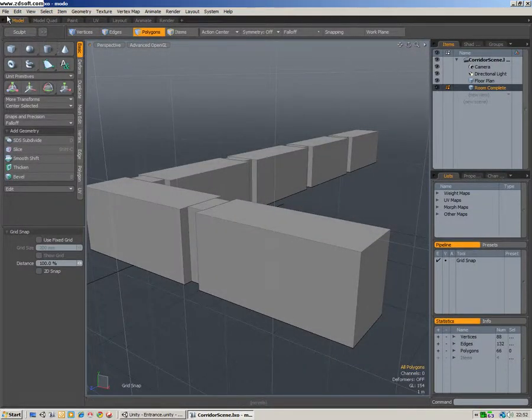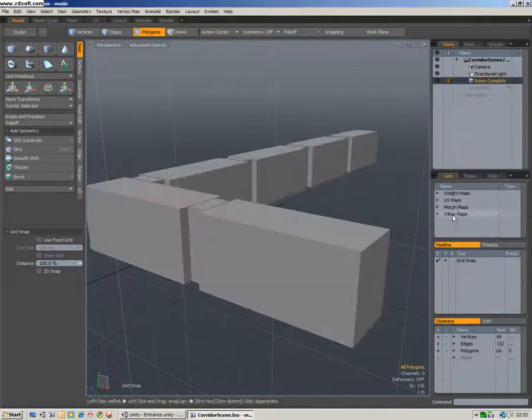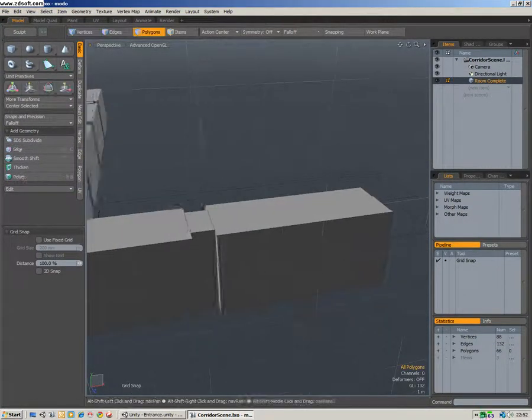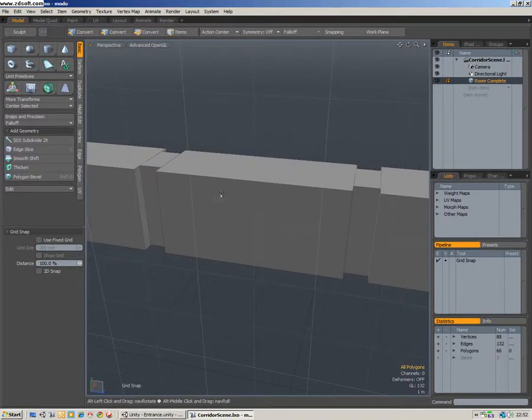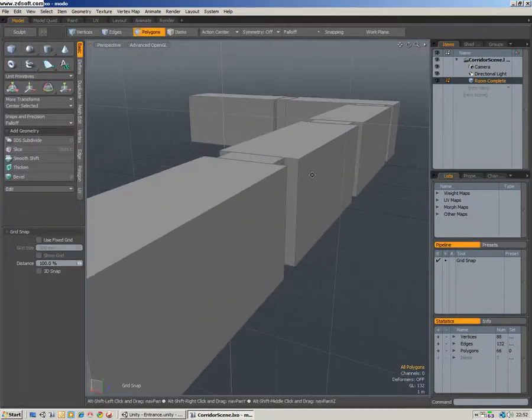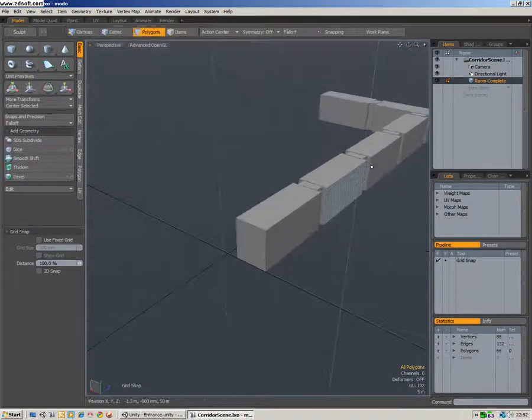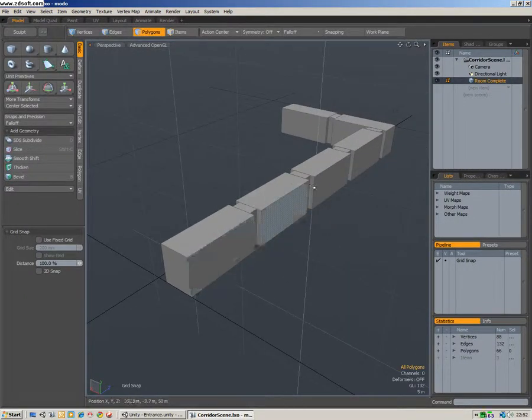So there you go. I'll just make a quick save on it. Now I can delete my initial floor plan. So that's basically the initial geometry, but all I've done so far is just made a load of boxes. When I invert these faces, if you were inside, you'd see them as walls. If you look down here in the statistics pane, you can see exactly how many vertices are making up this model, how many edges, and how many polygons.